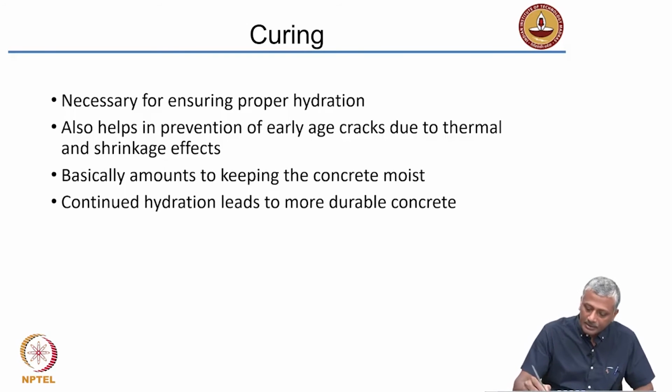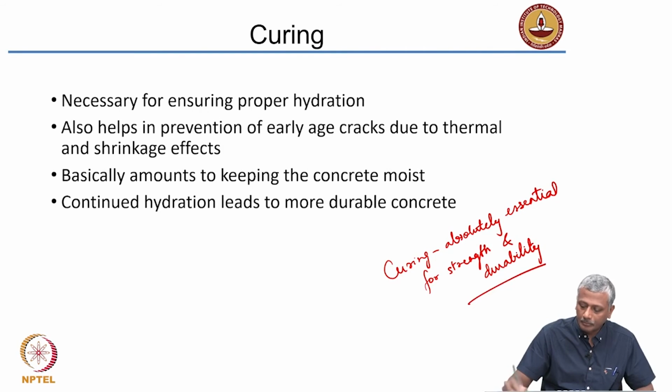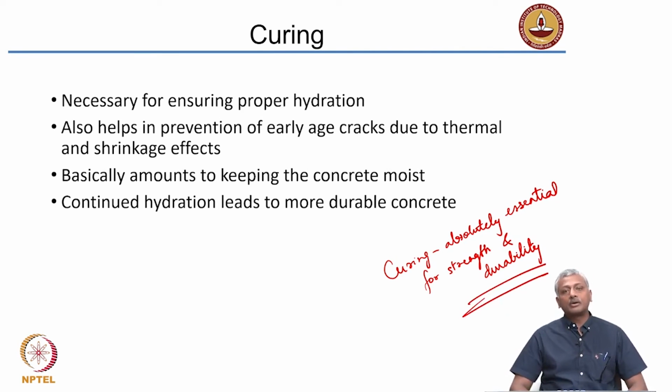So curing is absolutely essential for strength and durability. If you don't cure, you will not get a concrete structure that gains the required strength, and more importantly, you will not get the required durability. So continued curing, or keeping the concrete surface moist while it's hardening, is very important.